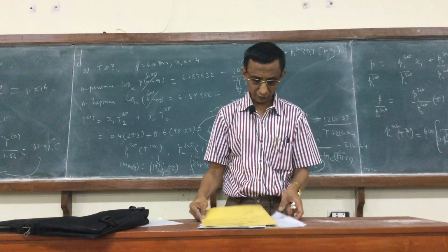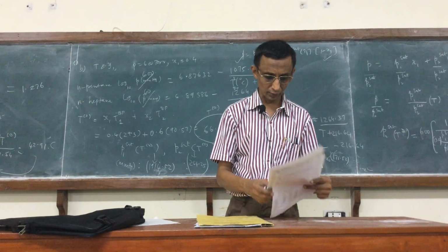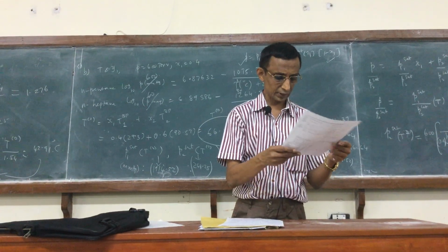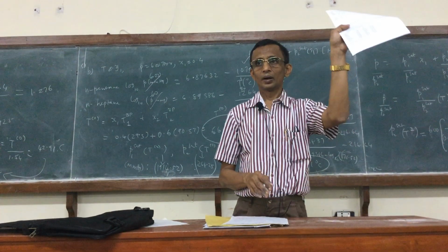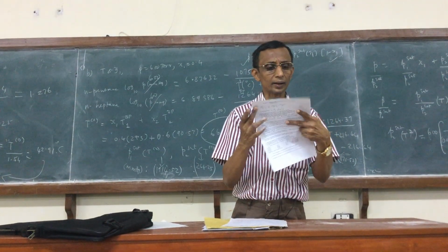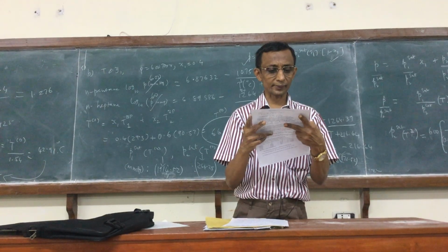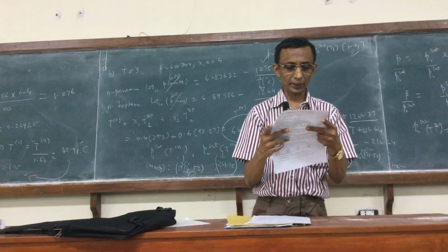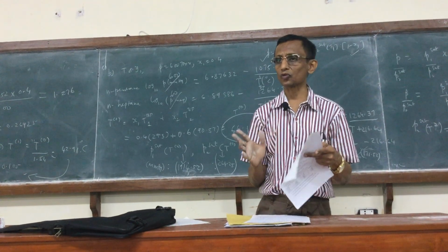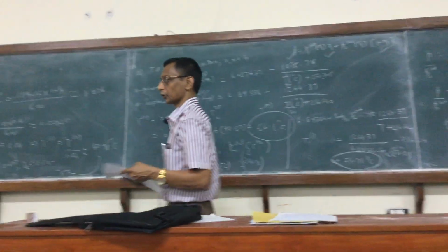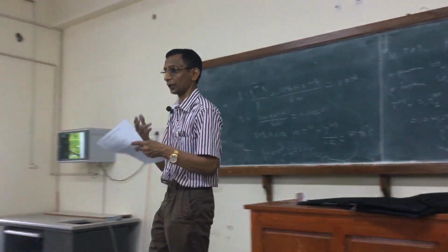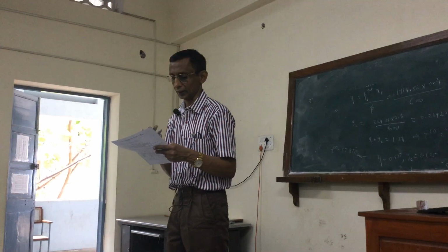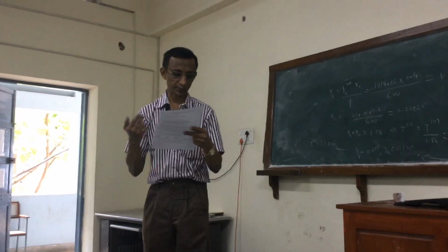Okay, if not, what I will do is move to the modified Raoult's law. There are several standard models that are given, the van Laar and the two-suffix and three-suffix Margules models. Basically, van Laar and the three-suffix are the most commonly used in textbooks because they are easy for computation, and they are not as familiar as the two-suffix Margules equation.